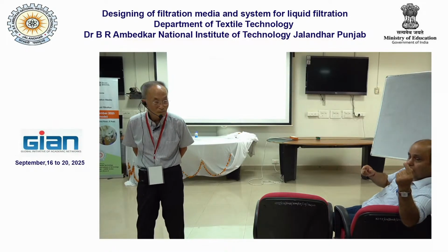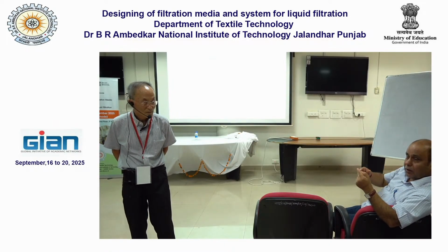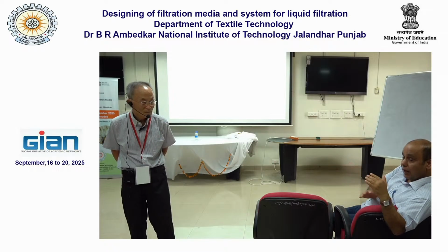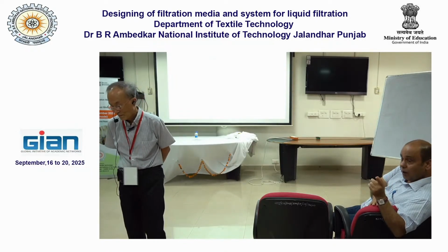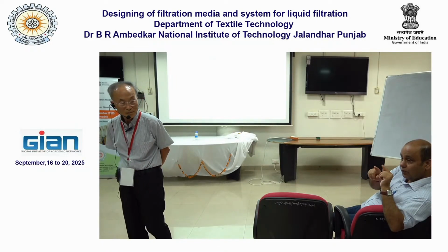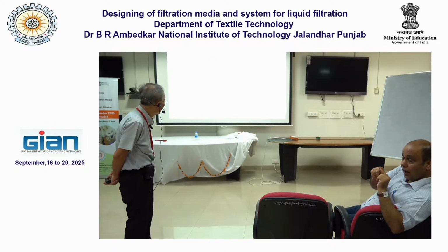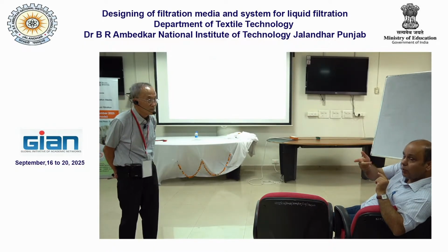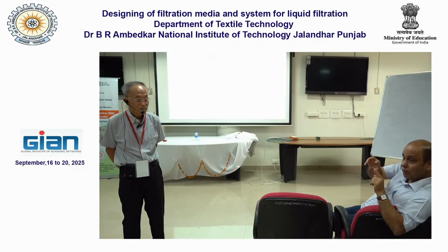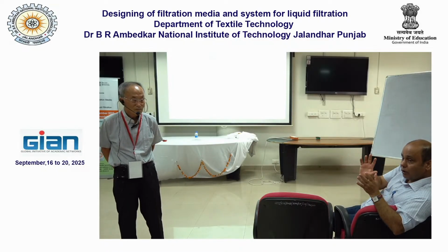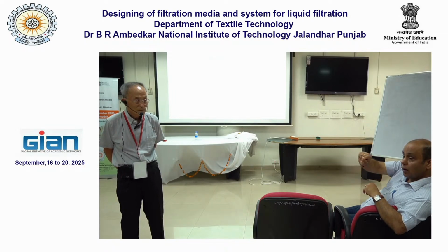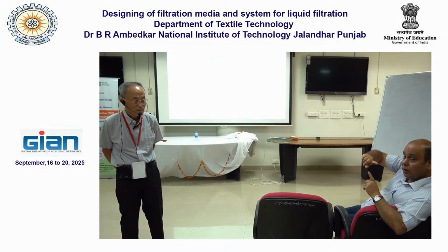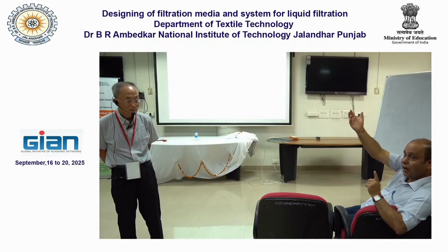Normally, if you go from coarse fiber to relatively fine fiber, you have a larger surface area. Larger surface area gives higher resistance. Higher resistance means higher pressure difference. The nanofiber is so fine that the gas molecules can also slip past, because gas molecules also play a vital role in pressure differential. So you cannot straight away equate it with the larger surface area, because nanofiber surface area will be many scales higher.